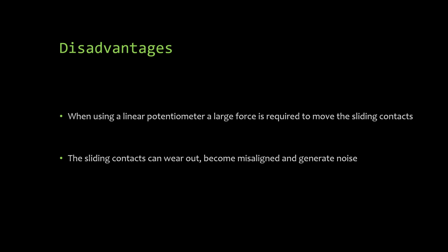So, as every system has advantages, it also has disadvantages. The disadvantages of the potentiometer are that while using the linear potentiometer, a large force is required to move the sliding contact. The sliding contact can wear out, become misaligned, or generate noise.